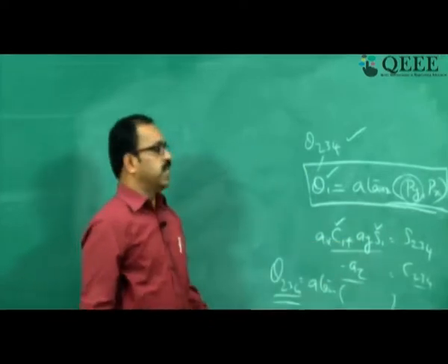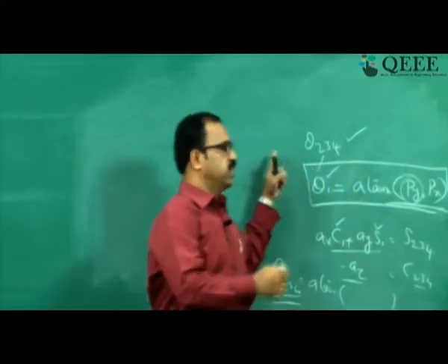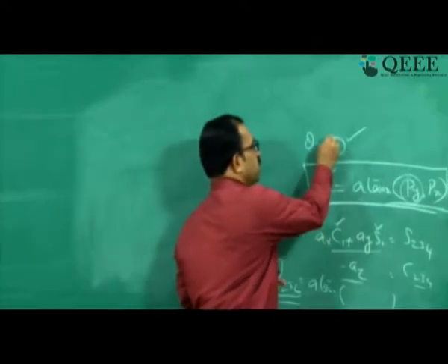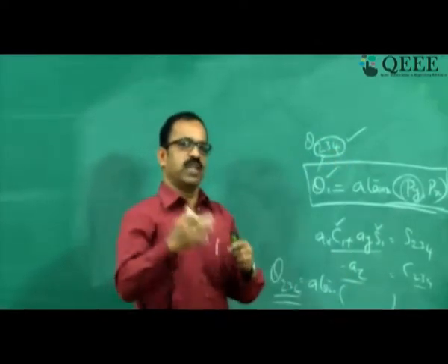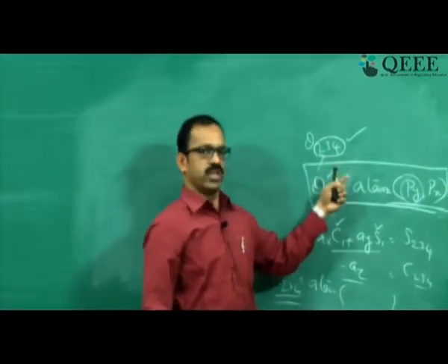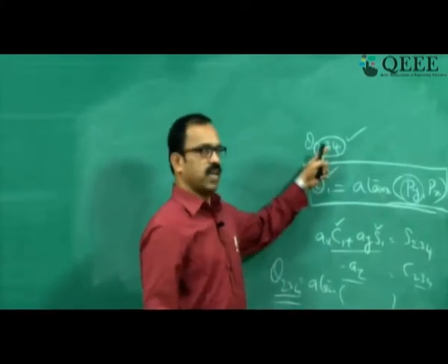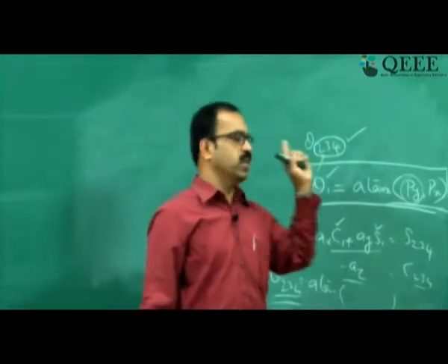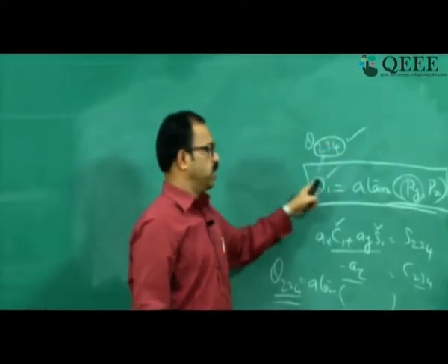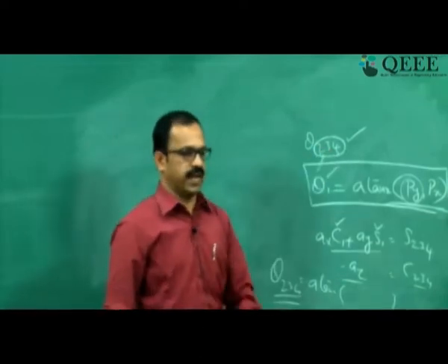And you can always see that whenever the three axes are parallel or intersecting, this kind of an equation arrives, 2 plus 3 plus 4 or 1 plus 2 plus 3, and that is when you can have a solution. If it is not coming like this, it is very difficult to solve, and that is why, to get a closed form solution, the sufficiency condition is that the three axes are parallel or intersecting. So here, because they are parallel, you can see that these angles are adding up like this.